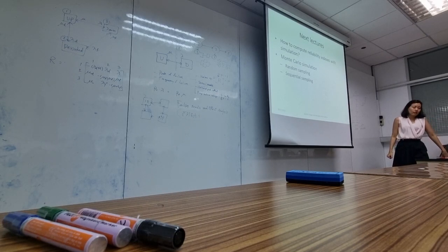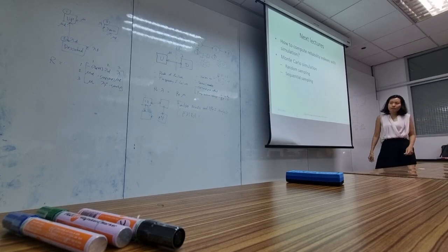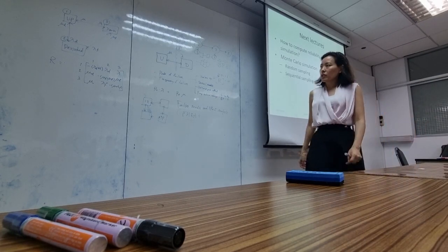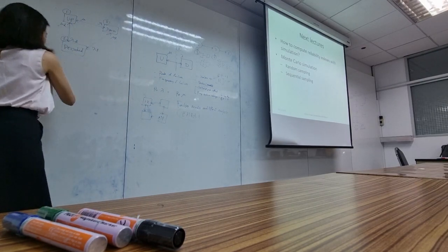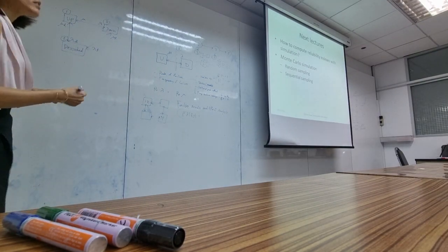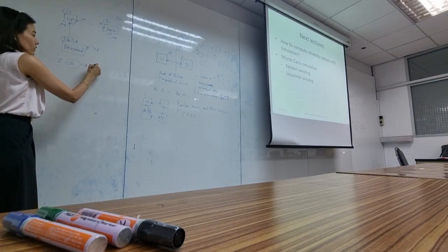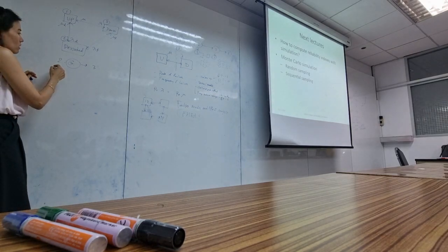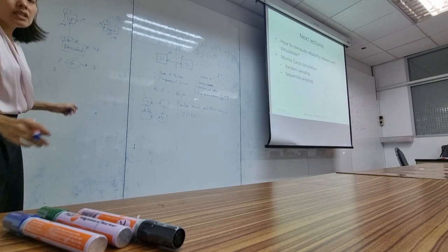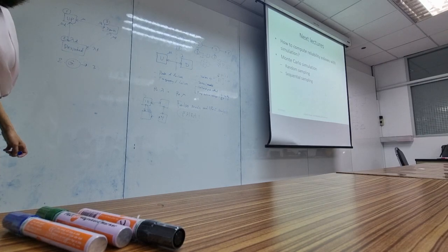When you look at the system, if you were to write down all of the possible states, say you have 2 generators, each with 3 states, you have 3 to the 2, 3 times 3, so 9 states that represent it.